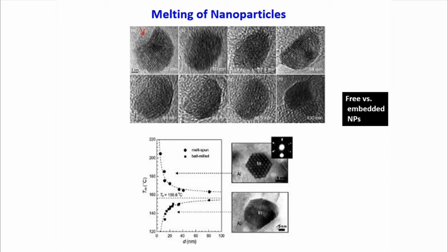So, you have something happening at the surface here. The contrast, which is mainly because of the crystallinity of the material, is lost, and that is why you can see an amorphous-like picture. There is a random arrangement of atoms, and slowly things start melting down, you can see here, and this part is slowly decreasing, is molten. Finally everything is molten after 130 minutes or so. So, that means a liquid layer forms on the surface, that part is clear, and then it grows inside.